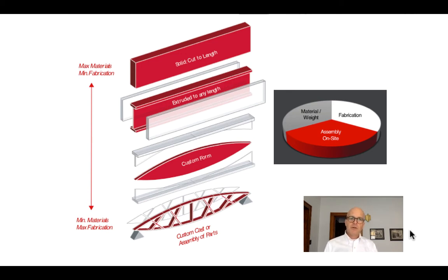The other thing we can do, though, is turn and look at the cross-section of the beam. And we've already done this a little bit. We looked at the difference between a rectangular beam of solid section, which is consistently dimensioned all the way across or all the way up and down its cross-section, and we said, hey, look, if the section modulus theory is right, then anything we can do to concentrate that cross-sectional area at the extreme edges of the beam, remember the technical term extreme fibers, will get more and more efficient because we'll be using the material only where it's the most effective.